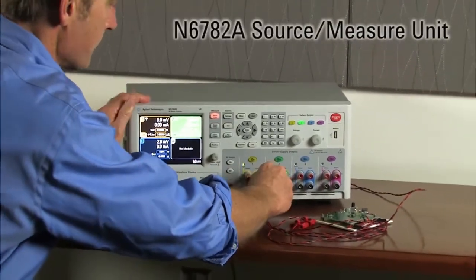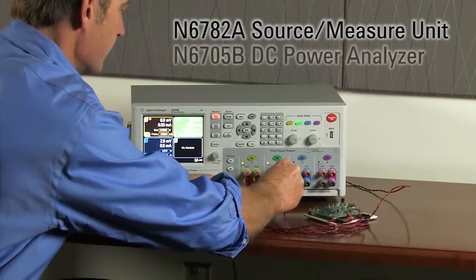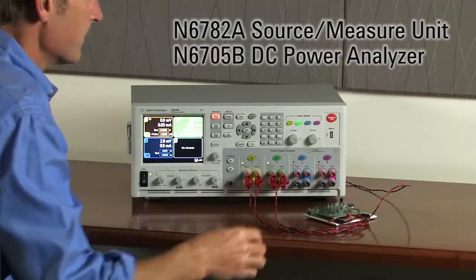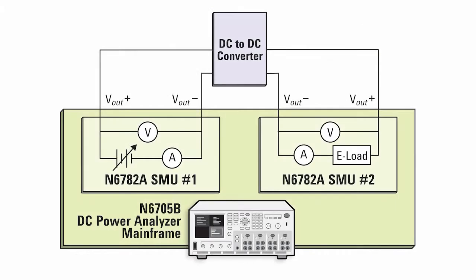The Agilent N6782A source measure unit installed in an N6705B DC power analyzer mainframe has specialized features for testing DC to DC converters used in PMUs. This is a modular system where up to 4 SMUs can be installed in the mainframe for maximum flexibility. Each SMU can be configured as a source or load and includes voltage and current measurement capability. Diagrammed here is the setup for testing a single DC to DC converter.